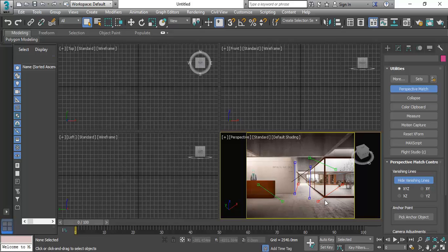The other X I'll drag to the bottom corner of this window, and then drag the other end again so that it follows, again, the line to the vanishing point. And then the Z as well, following that vertical axis there.